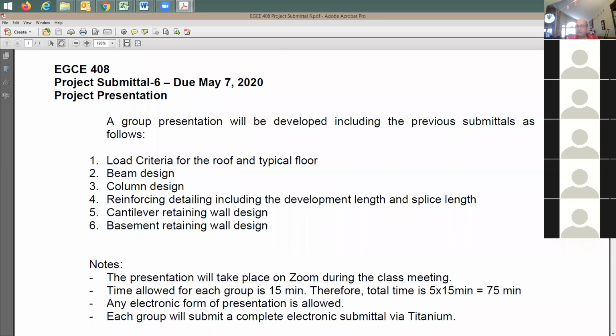I have a question on the design for the project. Yes. Just on the horizontal steel for the walls. Yeah. The spacing. Take it the same as the vertical spacing. Okay. And on the retaining wall as well? Same, horizontal? Yes. Okay. In reality, we design it for some lateral shear force, but in this case, we don't have it. So I'm just going to match the vertical spacing. Thank you. Okay.